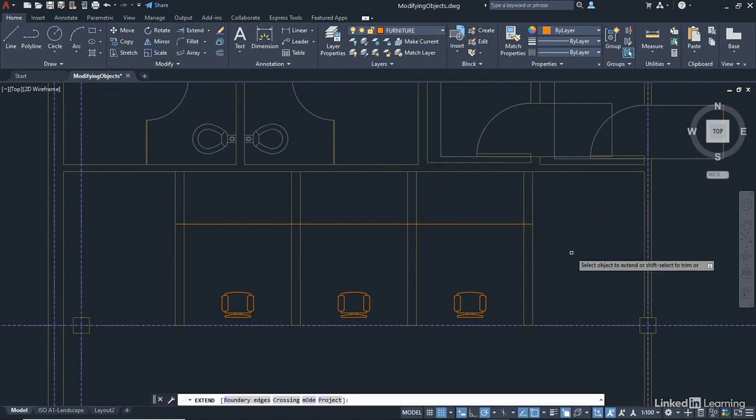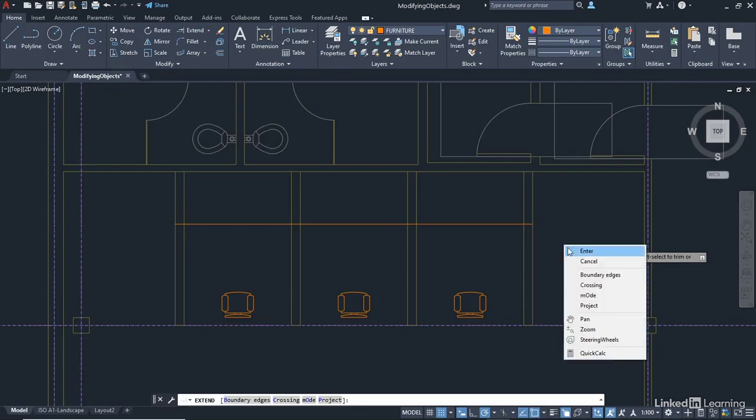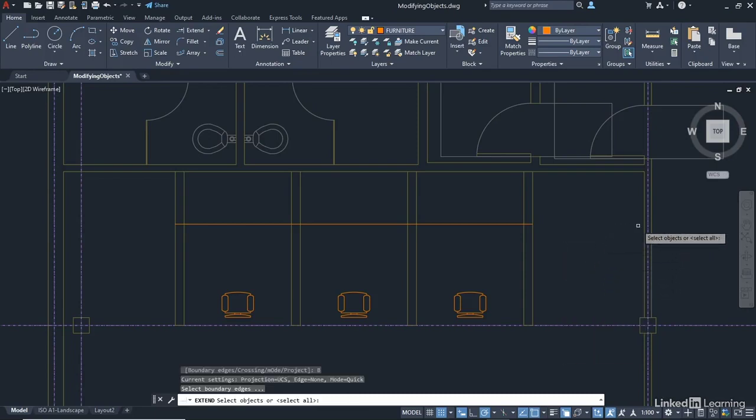Now, if you're using a newer version of AutoCAD, you will find that if I hover over that, it'll extend automatically. That's because they've changed the workflow of the trim and extend command. If you're using an older version of AutoCAD, you would normally have to right click and go boundary edge. You'd have to select an edge first like that and enter to confirm, and then hover there and extend like that, and then enter to finish, okay? In later, newer versions of AutoCAD, it extends to the nearest available edge straight away. Just be aware of that one.